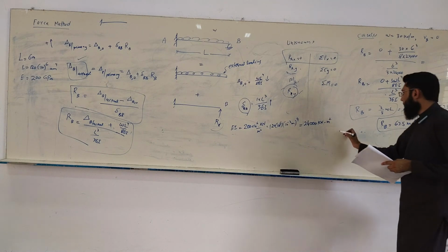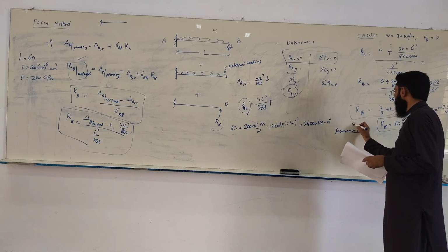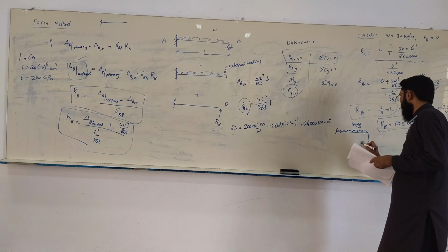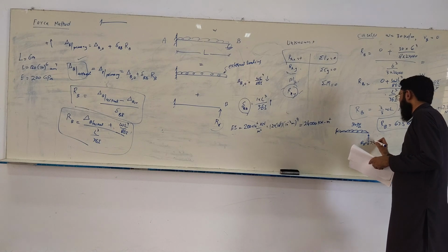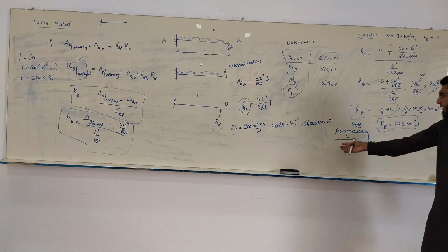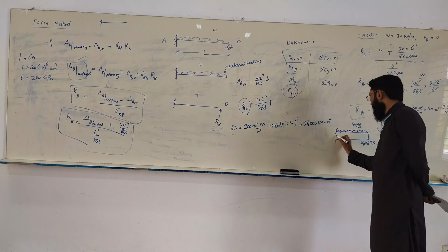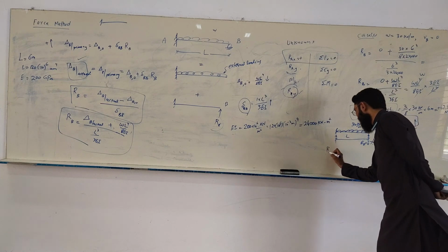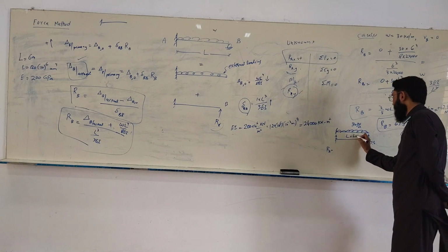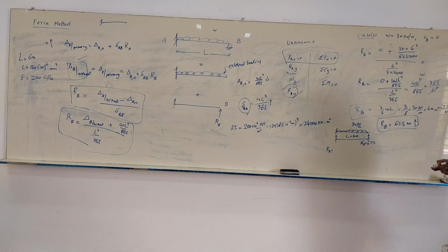So now it's simple, you have this beam, 30 kilonewton per meter and this RB is 67.5 kilonewton. It is 6 meter long beam. Now you can find out the vertical reaction and the moment reaction over here. Okay. What will be the value of RA? This L is 6 meters. So 180 minus 67.5. Okay.